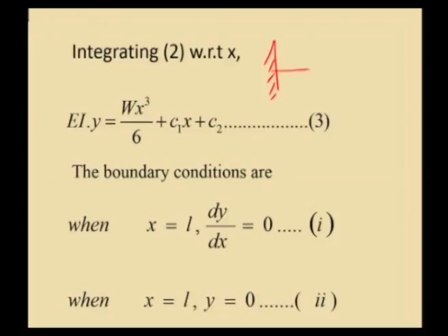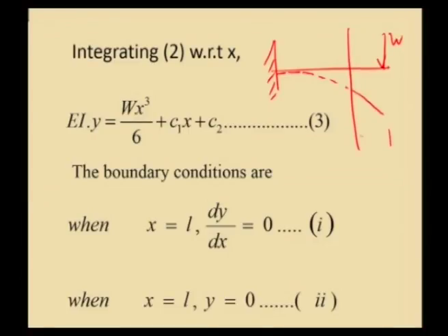If we take a cantilever beam subjected to point load, as we discussed initially, it will deflect like this. The beam will have 0 deflection at the fixed end and it will have maximum deflection at the load point at the free end, as shown in the figure, and we are measuring distance from the right end. So, we can generate the boundary conditions as, say, at A slope is 0 as well as deflection is 0, at B we will have values of slope as well as deflection as seen in the diagram.